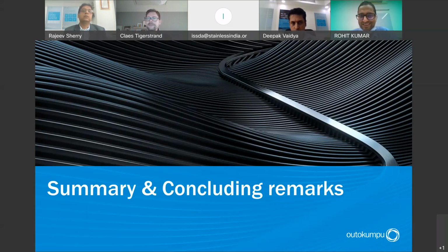I'm not sure if I'm the right one to answer it, but I would of course say that stainless steel has clear advantages there, especially on the corrosion resistance side, and also provides a more durable surface. But then it also comes down to whether you can benefit from a lightweight structure using aluminium. So in most cases I would prefer stainless steel.